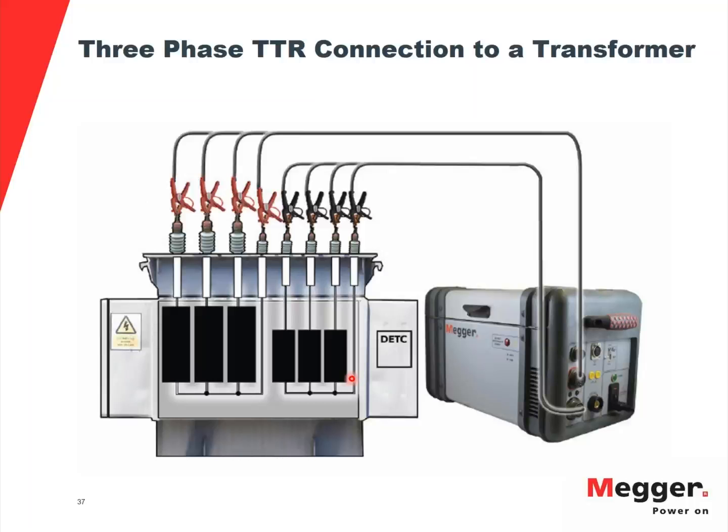When that procedure is taken in place, you will have a little bit of a DC component going back to your transformer. So if you really want to start from zero, avoiding any remnants of magnetization on it, you will demagnetize the transformer first, then you will do your AC testing, you will complete your procedure with the DC testing of winding resistance, you will demagnetize, and then you will energize the transformer again.